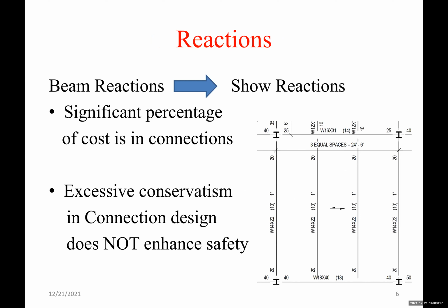The first important thing that's related to connection design is beam reactions. So show beam reactions on the drawing, which is becoming a typical practice these days, based on what I see.